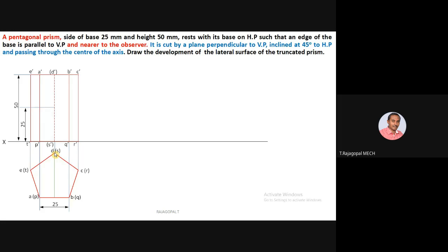We are in development now. He may have told you that simple position is the fundamental basic from unit 2 till unit 5. So till unit 5, you have to be very confident in simple position. This is the first and foremost step of any problem. Now we have marked this 25 mm dimension, which is the center of the axis. Now you can draw the 45 degree inclination line passing through the center of the axis. Make it 45.